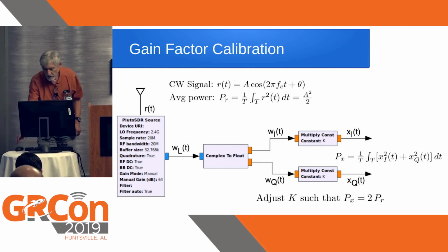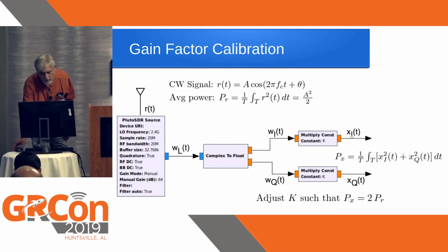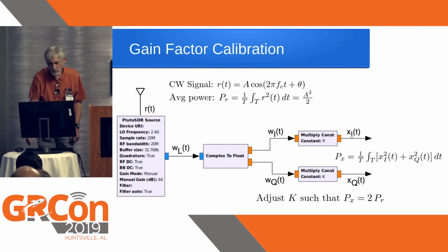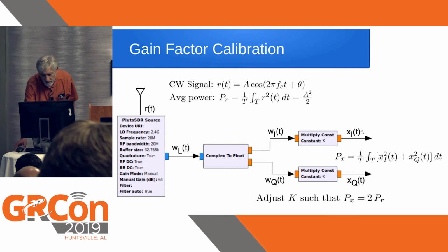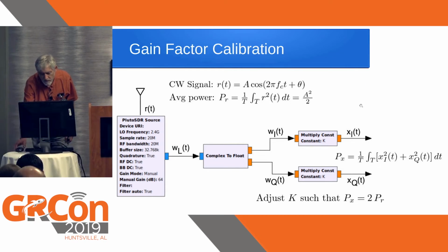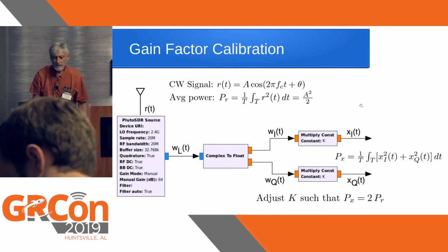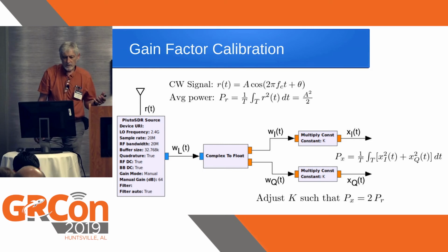You have one input here, but you have 2 outputs because you're now operating in the complex low-pass domain. So what do you do? Should that output here have the same amplitude as this input, but because you have 2 of those, you're going to get too much, possibly? Or should you make it such that you evenly split up between this one into those 2 back here? And after all, there is going to be a frequency involved for the transmission.